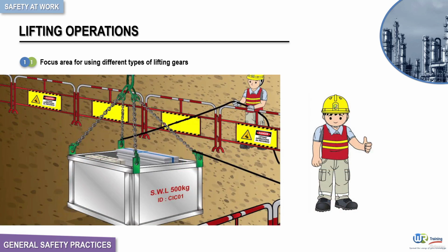Loose loads, as in this case, should be packed and placed in suitable containers before lifting. The containers must be structurally sound, tested, and examined by a competent worker. And then suitable slings must be used for lifting to avoid container tilting.